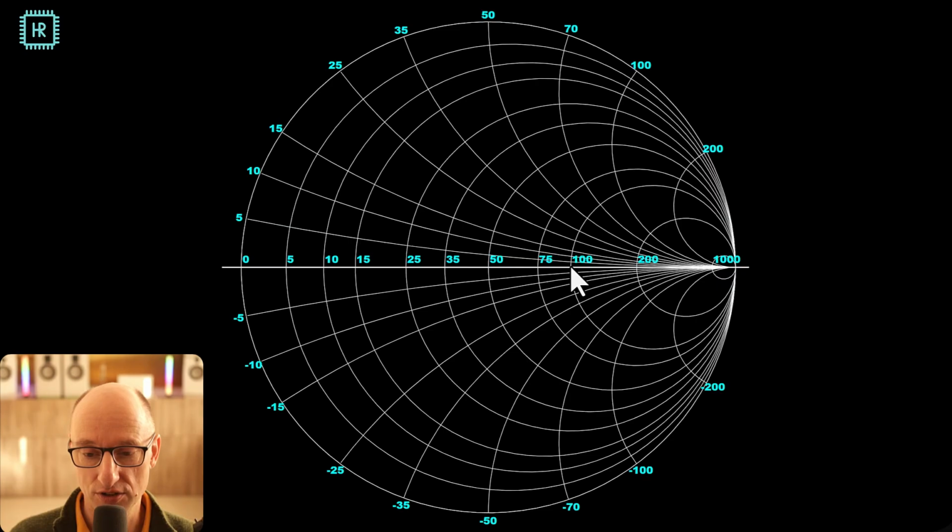Now the impedance will start moving clockwise around that 75 ohms in a circle. It will cross the real axis and it will just keep continuing. So what's interesting about this, if I pick a value somewhere in the middle between 100 and 50 ohms, then it will start rotating from 100 around that point in the middle and end up at 50 at a certain frequency.